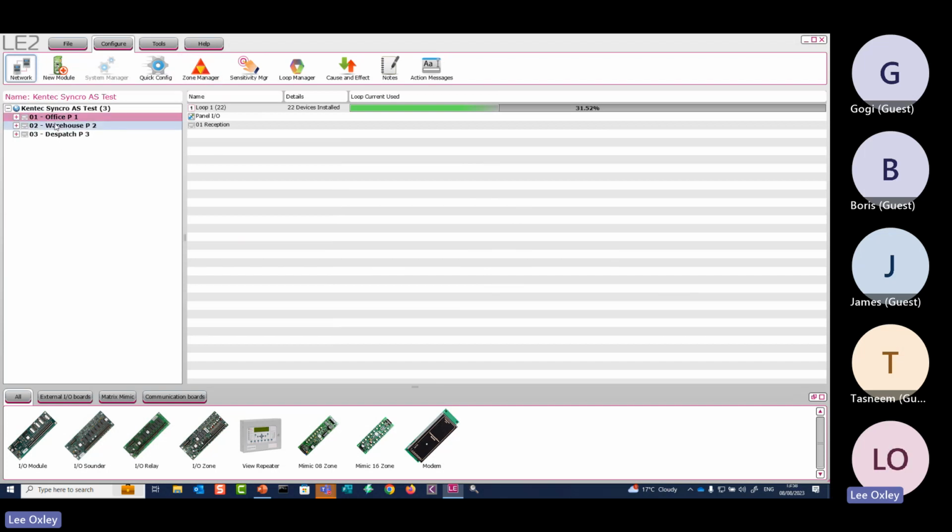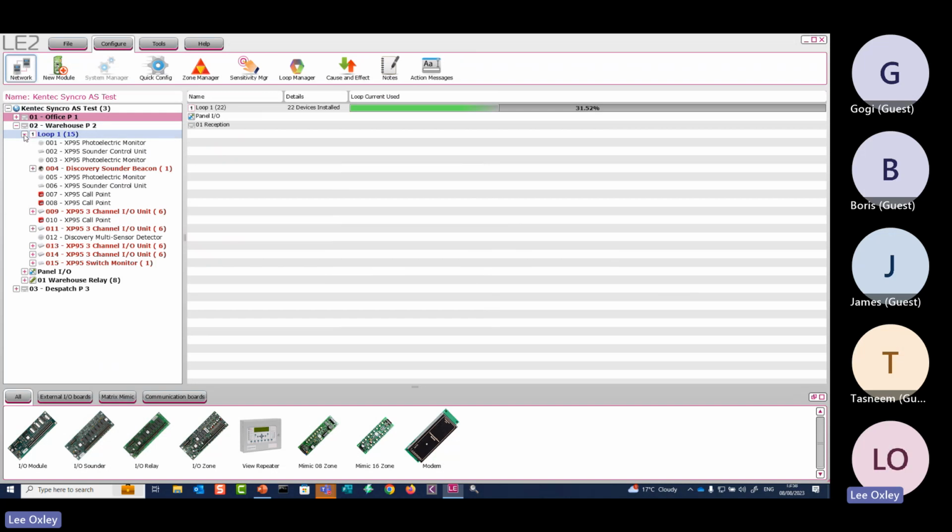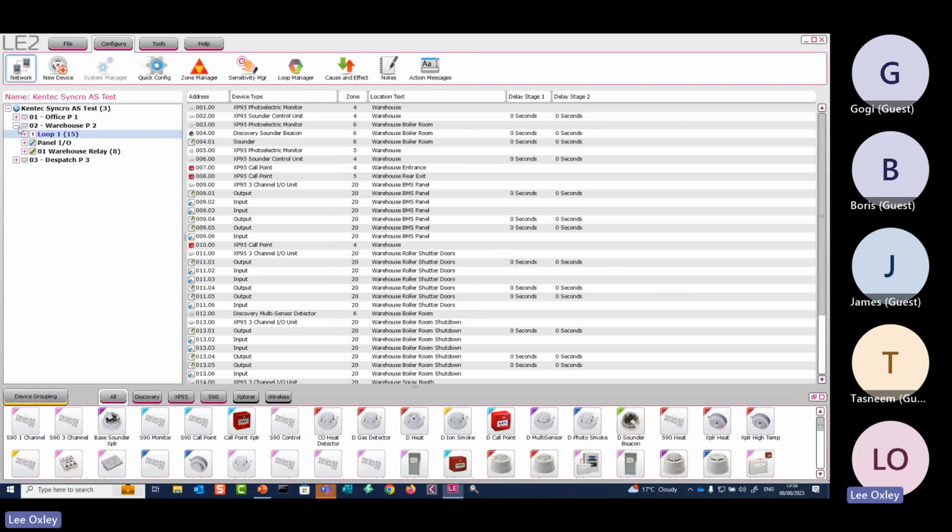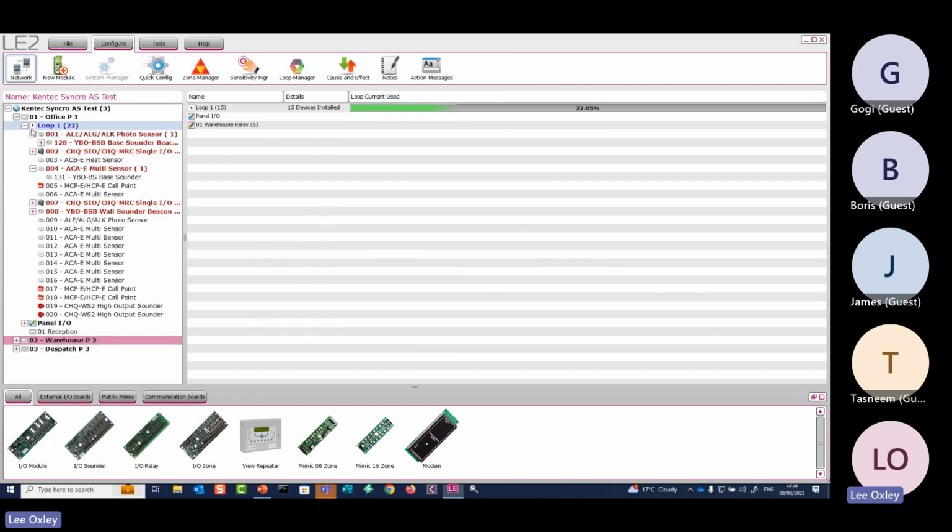Like for example, in this warehouse, let's say there are some issues. Let me have a look. Tell you what, I'll go for the multis. We've got some multis in that link corridor. Maybe they've got some fault lifts going through the link corridor. We've just installed these multis and they're having some false alarms. So maybe you want to say, okay, then we'll have them as a heat detector during the day and back to a multi during the night once the building's closed.